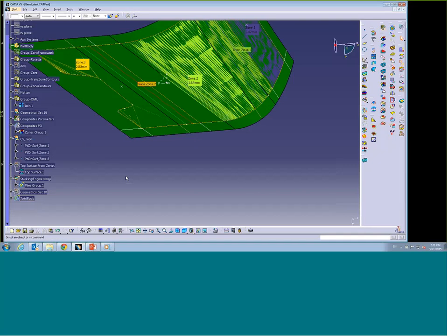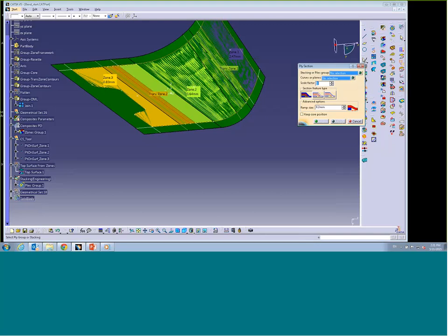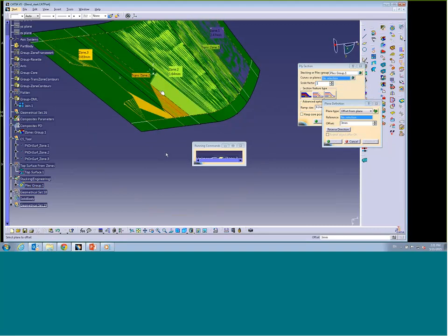All right, so at this point I can also use different kinds of design review tools. We've seen the ply exploder tool, an extremely convenient thing. There are some other options available. For instance, I can do a cross-section. I want to go through the plies group, using curves or planes, so I can create a plane. Let's say I want to go through the middle.